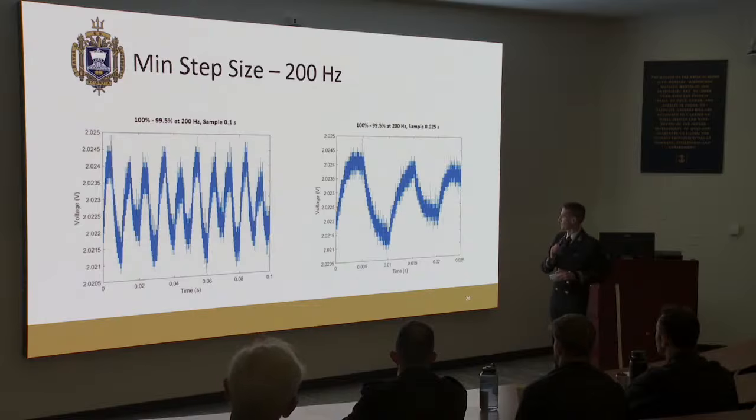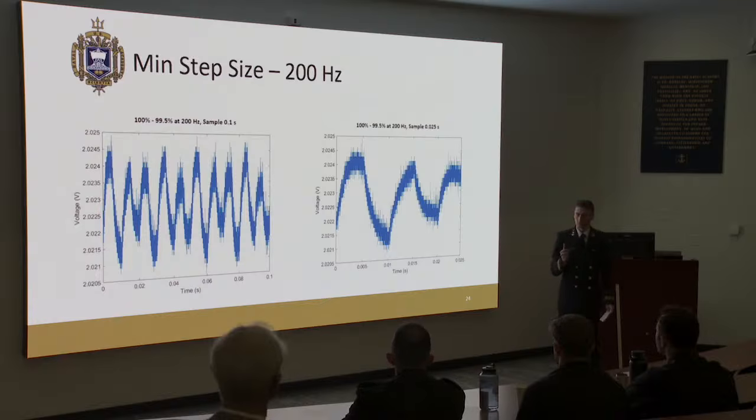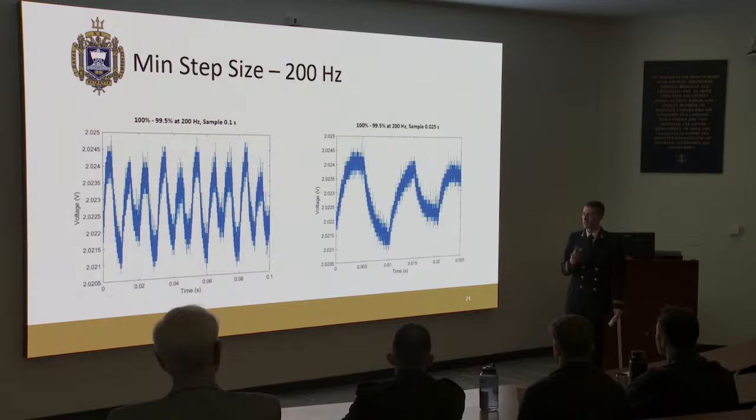A lot of noise there. It's kind of wiggly, washy, not very pretty step waves. We eventually, after lots and lots of testing, were able to determine that this isn't actually from the LPT system or the PV cell. It was being internally added by our data acquisition device. So the only solution we had without buying a new DAC was to post-process this information.